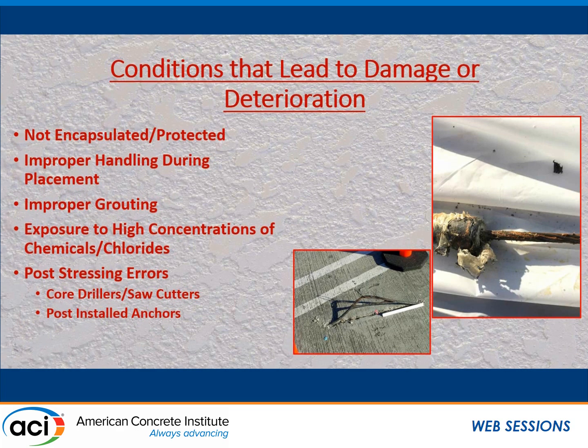There are a number of things that could cause damage or deterioration to post-tensioning. Some of the slides I'm going to show today are specific to damage. Some of them are specific to relocating live tendons, particularly in cases where you are repurposing a building. So you're cutting through an existing post-tension slab and putting in an atrium, a stairway, or some type of mechanical opening.